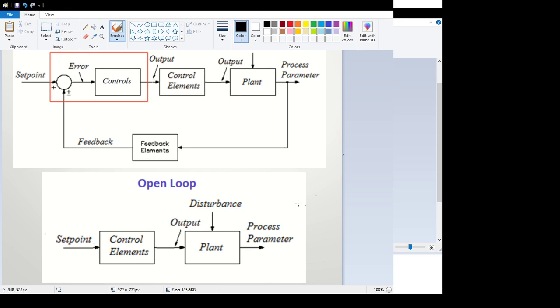Alright, so in this video we're going to look at first an open loop control, and then we're going to look at closed loop control using proportional control. So the open loop, we're going to have a set point. My set point is going to just be 5 volts for each example that I'm going to do in this video. So I have 5 volts here, and I'm going to feed this out of my PLC. So I have my PLC here that's going to send out an analog output to my system.